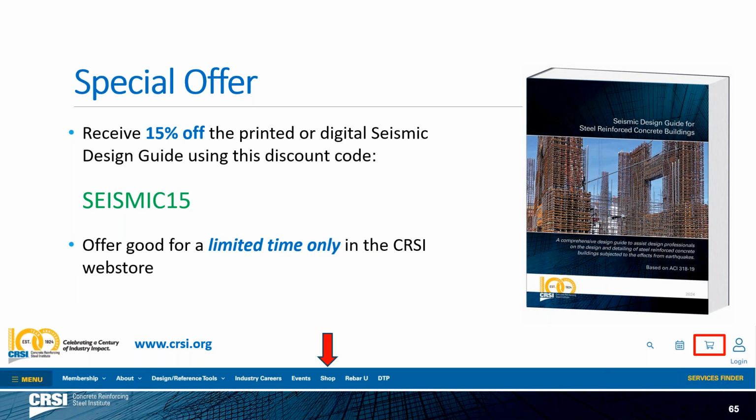As per ACI, the maximum fy that can be used for columns under axial load is grade 80. Oh yeah, this is another good one. Even if you're using grade 100 reinforcement, which is permitted, in a structural wall, do we have that 80,000 PSI limit?